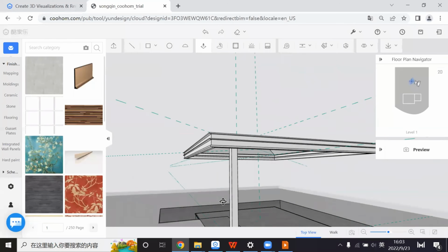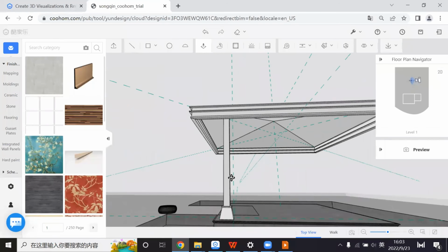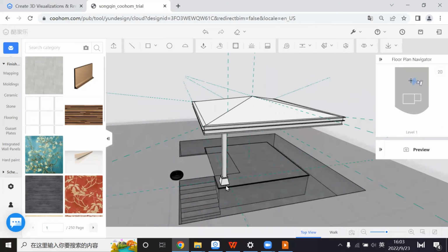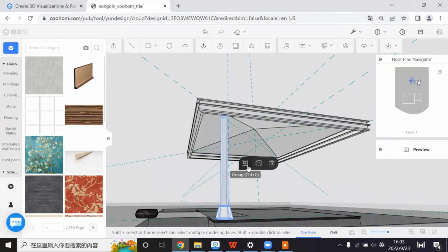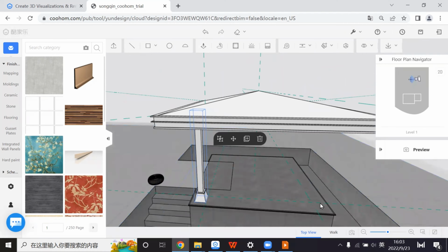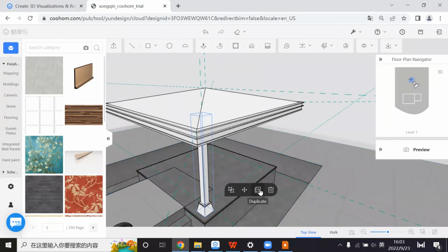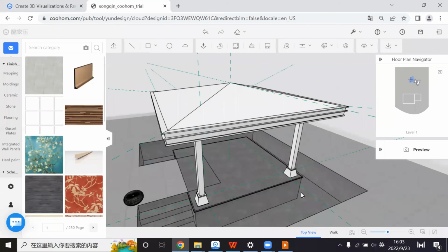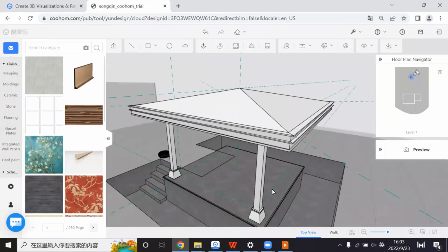The same thing happens when you want to draw out the other parts. Of course, you can hold down the shift button, double click, get a duplicate, right? And click. Now I can have another round. Just now, how much is the distance to edge? 400, I believe. Yes. Okay. Click, duplicate. And just need to remember when you duplicate, point to point. Click this point to put this point. Okay. Same thing here. Duplicate.